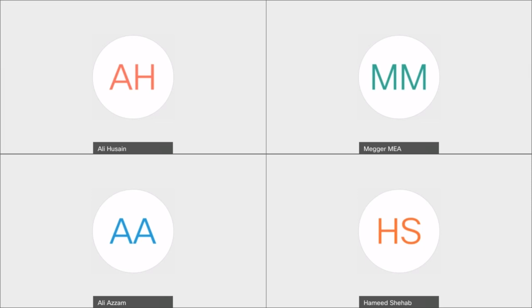Of course, the best thing is to compare a value injected at 50 ampere with a value you are testing at 50 ampere, and 100 ampere with 100 ampere. It will be the best way, but it's not always possible to do that. Maybe the test equipment they use in the factory is much more accurate at 50 ampere than the test equipment you are using on the site. So on the site, you may refer to injecting higher current to get the same accuracy as the factory itself.